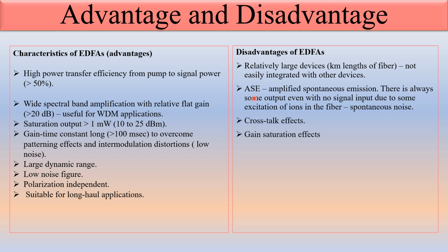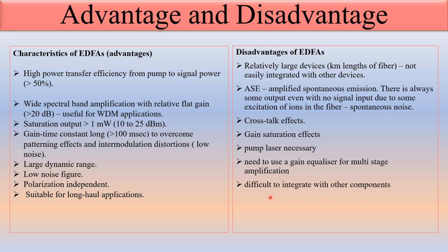Crosstalk effect, gain saturation effect, pump laser necessary. Need to use a gain equalizer for multi-stage amplification. Difficult to integrate with other components. Dropping channels can give rise to errors in surviving channels. So these are some advantages and disadvantages of the EDFA.